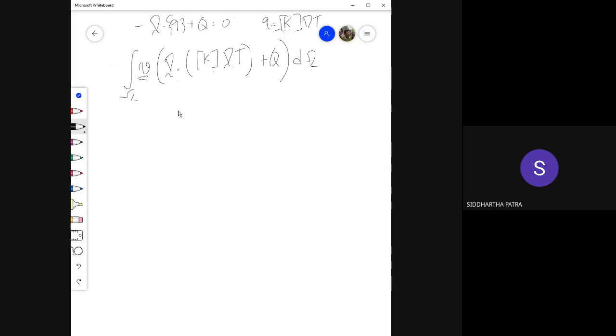Now this integration would be 0 within the domain, or the volume, but at the boundary this may not be true. So I need to add boundary terms which look like this in gamma q. So I don't need to take care of gamma t, because for gamma t v is already 0.